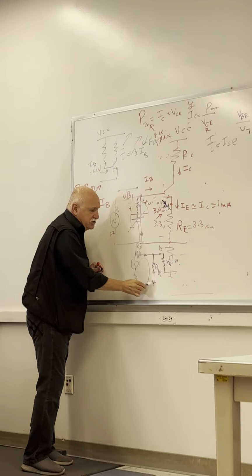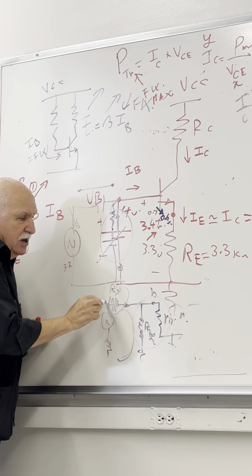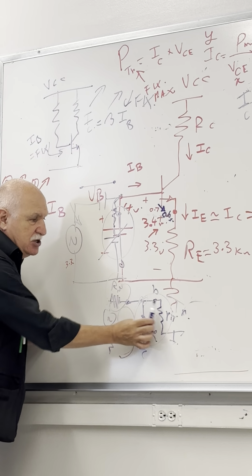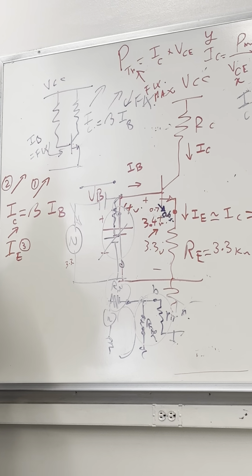VI is called the input voltage to the circuit. So this is your main amplifier. VI is the net input voltage reaching there. VI is different from the signal VS, because if that source happens to have a resistance in there, RS, it forms a voltage divider with the input. So the signal in here might be large, but the signal here can be smaller because the input resistance attenuates. It reduces the original source signal.